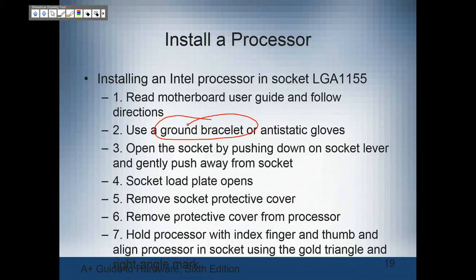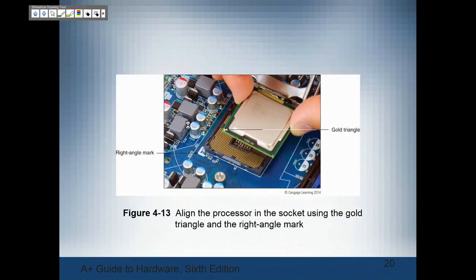If you drop it and it doesn't go in, you need to be sure that you've got pin 1 lined up and that the pins are lined up on it. In the good old days, the bad old days, we used to have to actually put pressure on the pins to put the CPUs in, which also meant that you could bend the pins. That was a real issue. The zero insertion force and the LGA, the land grid arrays, where instead of receptacles in the socket itself, we actually have little lands that stick up that connect to the CPU itself.